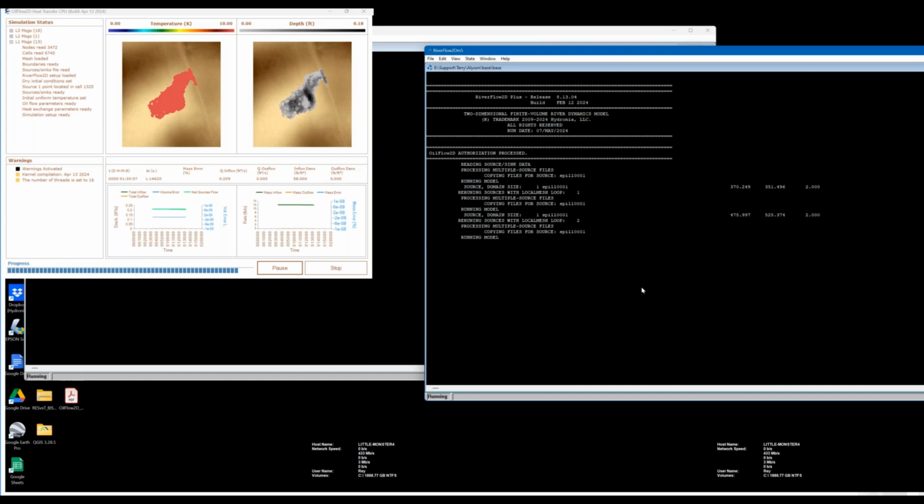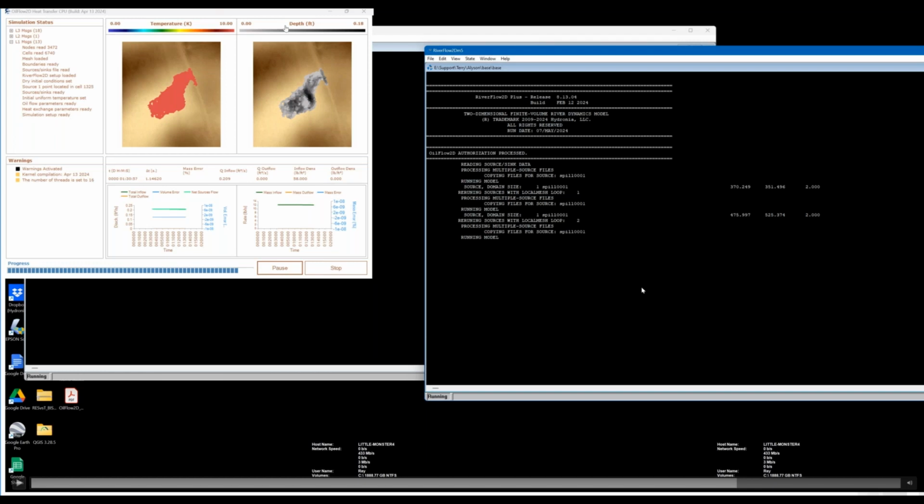You don't need to worry if the mesh is going to cover the whole spill area. Each spill will take advantage of the information you have in the terrain, and then it will expand the domain according to what it needs to be able to contain the whole fluid here.